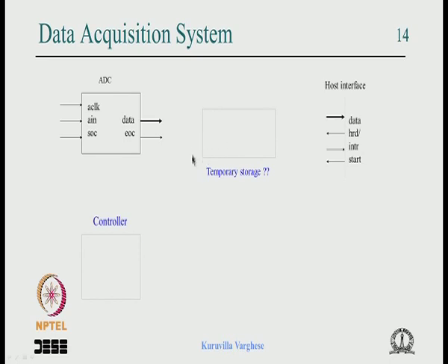In a dual port RAM you have two data buses and two address buses. So we can use one bus to write and the second port to read. But if you think for a while, a RAM allows random access.